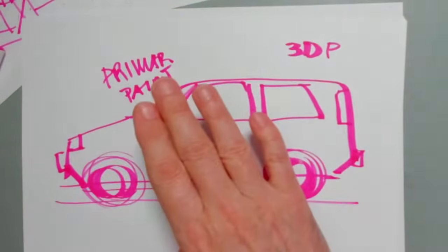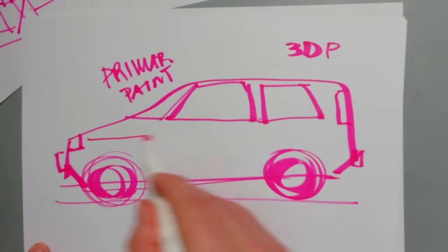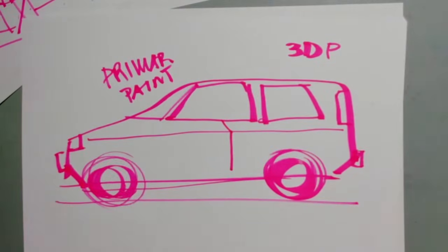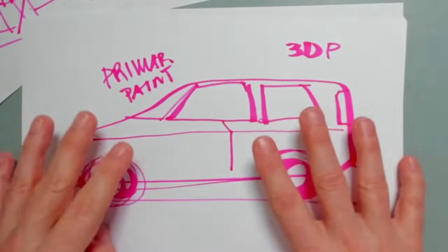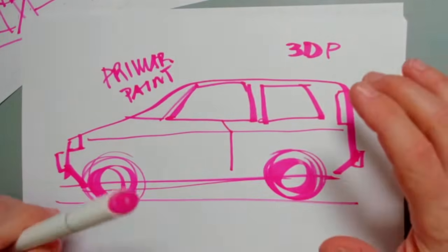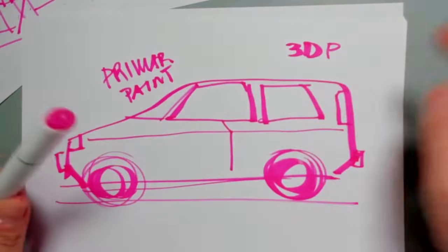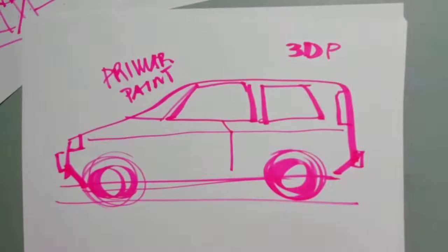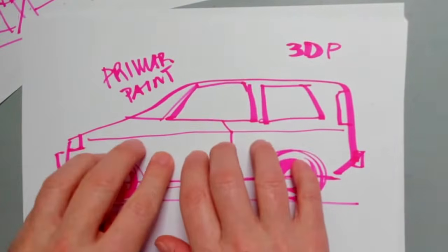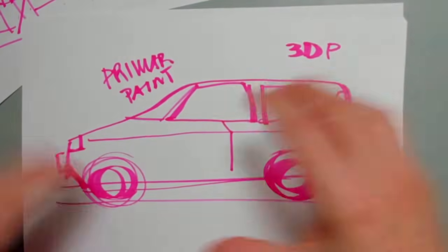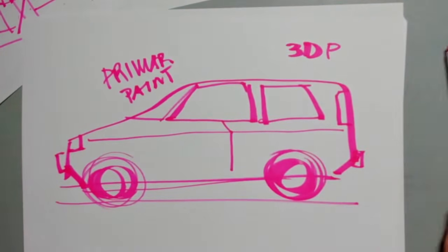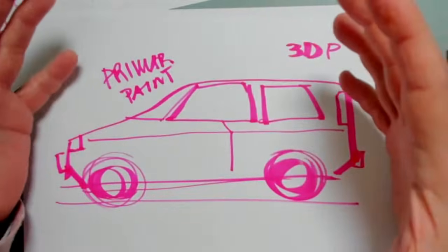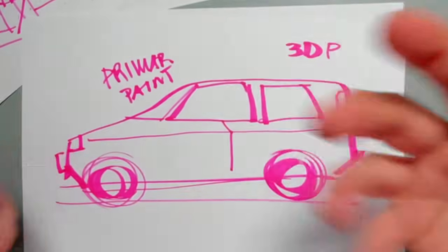Then they will sandpaper the surface. If you have a section that is like that, they will reproduce it by sanding that section. They will put the tape, they will really try to do their best to have exactly the model you milled out. And once we have that with primer, they will start masking, and we follow the classical spray paint process, which means I put the black color for the glass, the real color that we want onto the body, and then at the end you put together all the other parts, and then you put the transparent paint, the varnish, and that's how you get a clay model painted that looks like a real car.